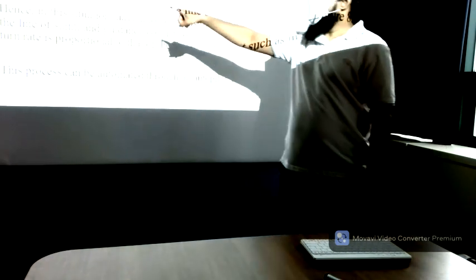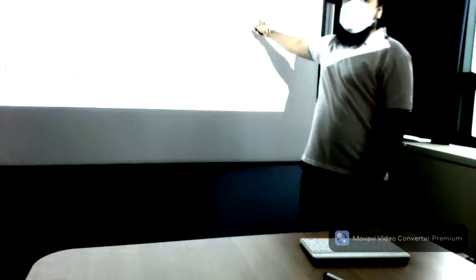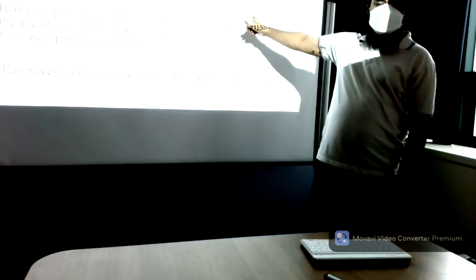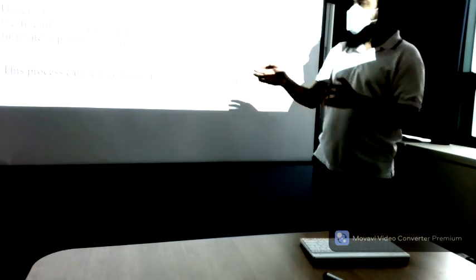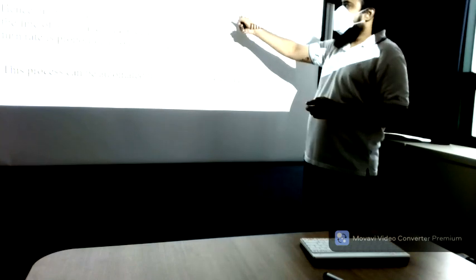An effective way to guide the homing missile is to steer it so that its turn rate is proportional to the turn rate of the line of sight. Our objective is to make the same turn rate.